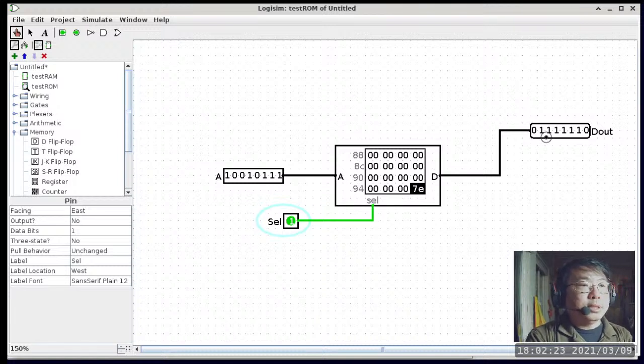The TTP has no endianness because it has no multi-byte capability. Everything is 1 byte wide. We only have to worry about endianness, little endian versus big endian, when some parts of the processor have a bigger size than other parts.